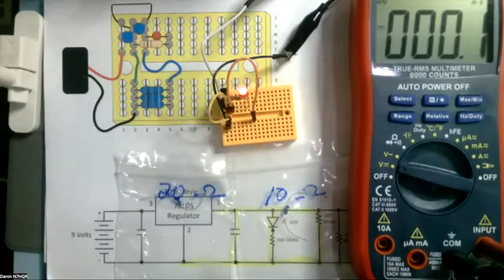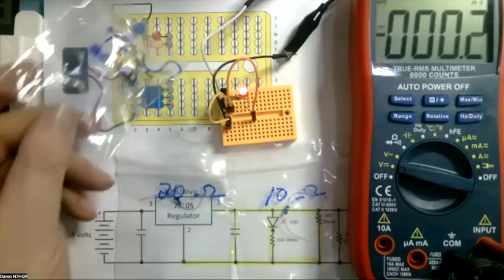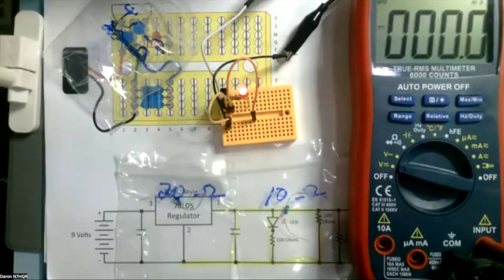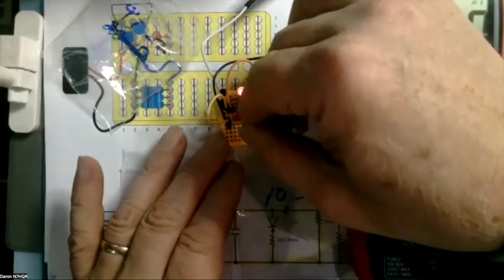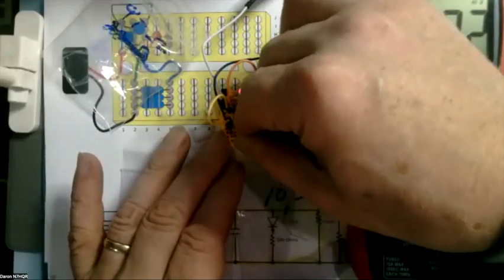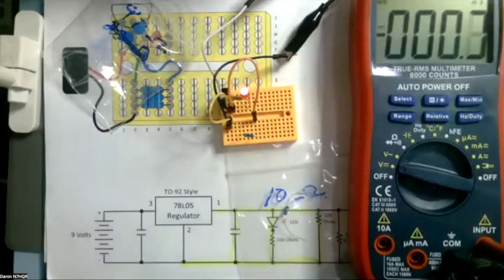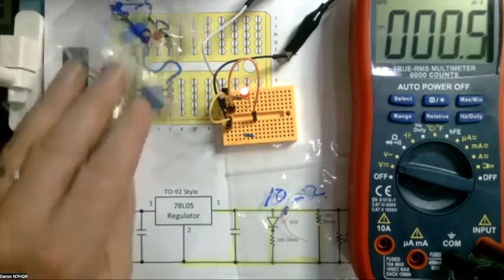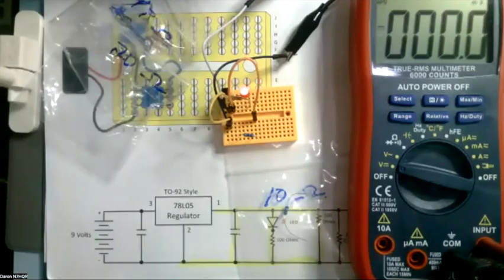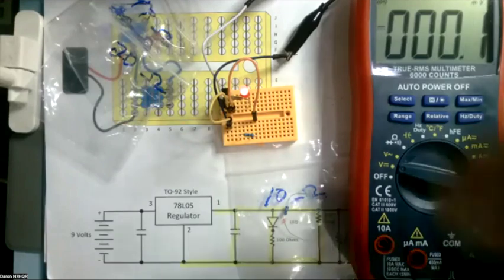Thank you for making these really small so that my eyes struggle. Well, notice I put them in bags and I wrote big. I appreciate that. That helps me a lot. Do you want any power on these yet, or are we just going to measure resistance? Well, right now we're going to measure resistance, but then we're going to apply power and measure the current. Okay, so there's our 47 ohm. And I will add the 20 ohm in series with it.